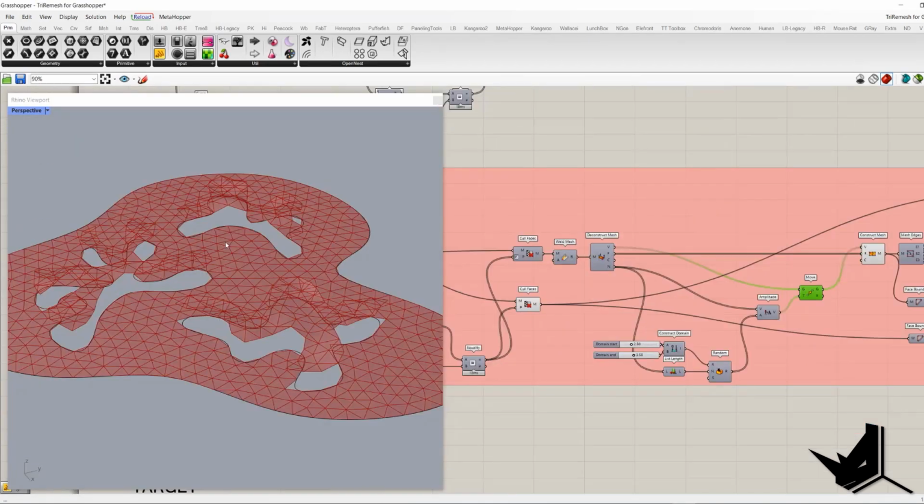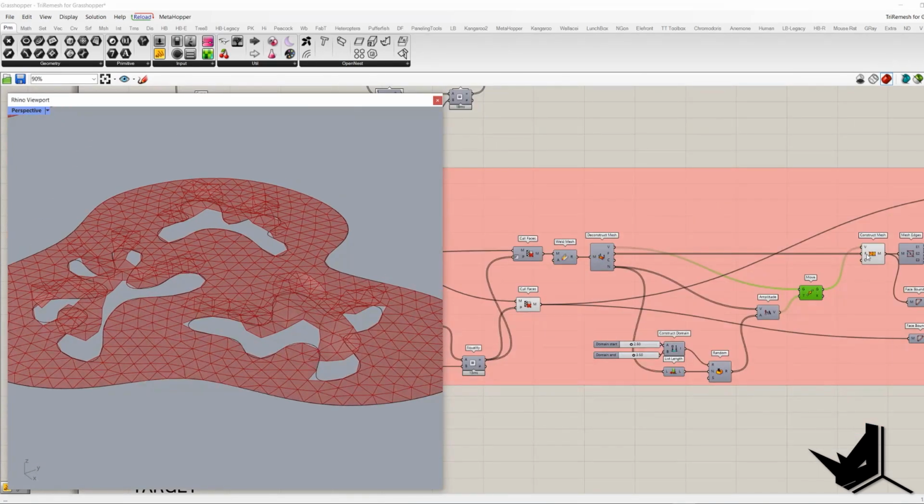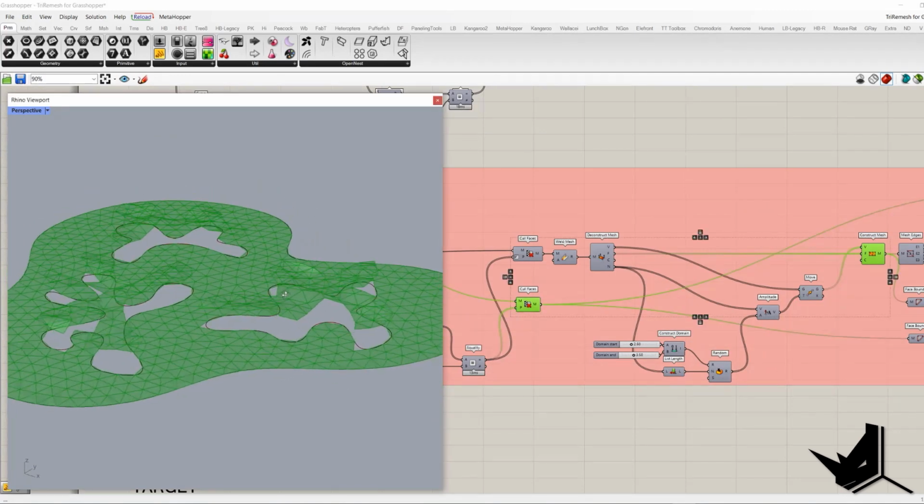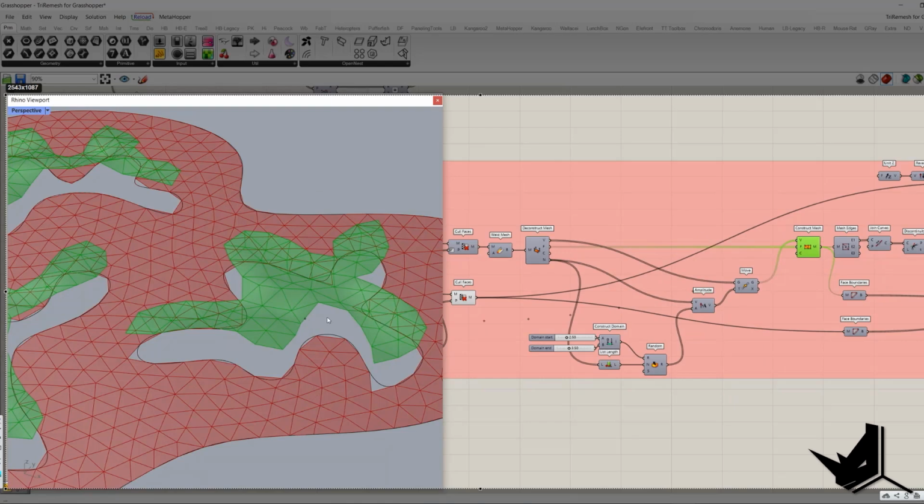the other mesh. All right, so now as we have these 2 meshes, we need to combine them somehow. So the best way to combine these 2 meshes is to take out the edges of this mesh. Actually, we'll take out a naked edge, join them, then find the discontinuity of that curve. Using discontinuity, we'll have all these points, and then these points we're going to project on this mesh, and the projections will be along z vector because we moved them along z vector.